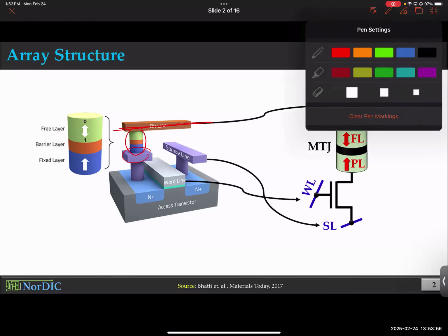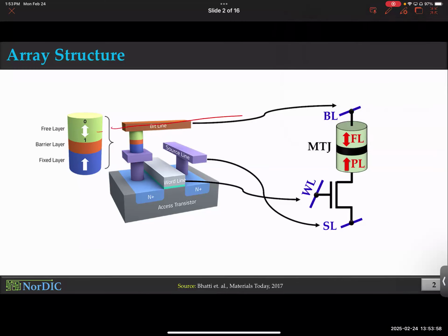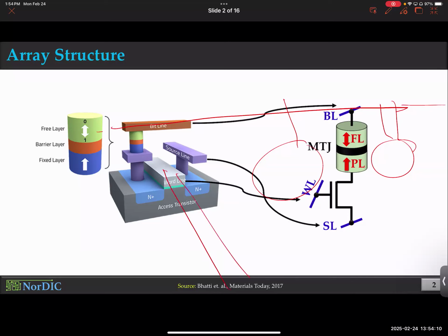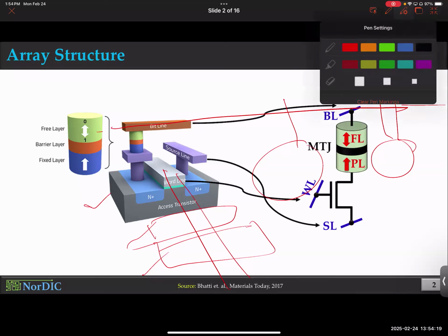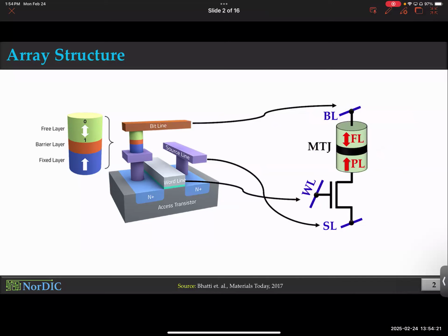Okay, now, for example, if the bit line runs this way, the other cell within the same column will share the same bit line. And if the word line runs this way, you just replicate these cells, like the same transistor, over and over again, and you see how the word line is shared, right? Can you visualize this? One interesting approach would be to just take this image and copy paste it to the right and in front of it, and then you can visualize in 3D how it really looks like.